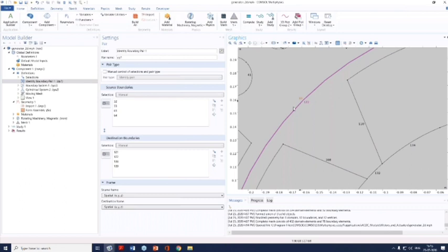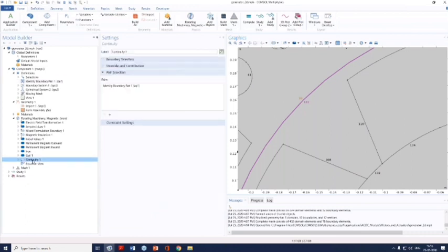So whenever you are using this form assembly, the identity for each boundary will not be treated as an internal boundary, but it will be having a collection. You will be having a collection of two overlapping domains, and in that case, in order to ensure the field continuity across that particular boundary, first of all, this identity pair needs to be created, and after that, that same pair needs to be selected under the continuity boundary condition as well.